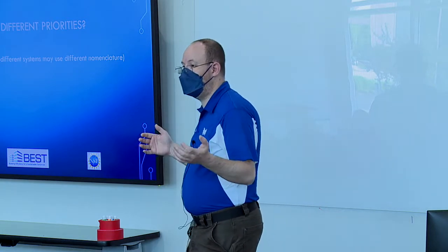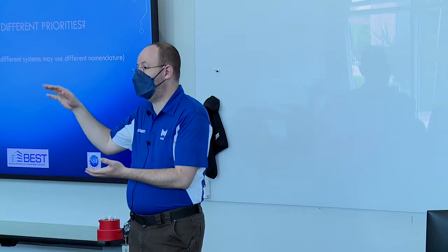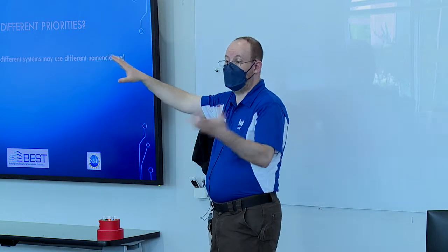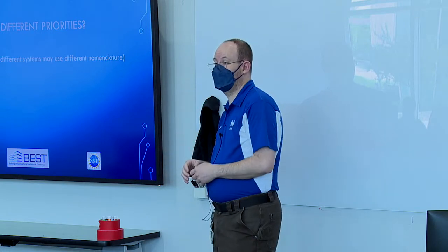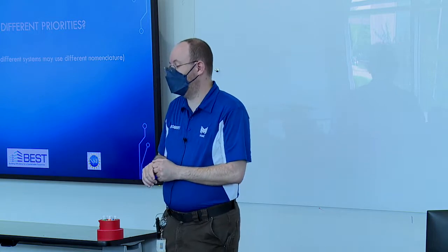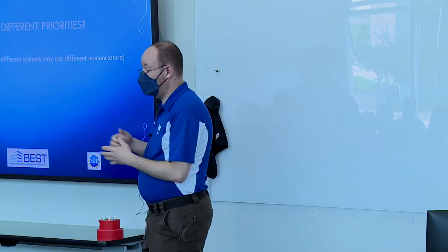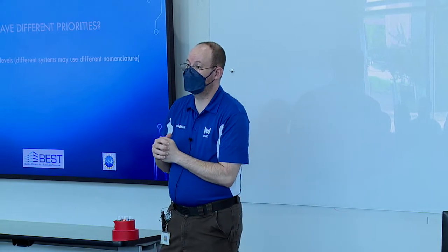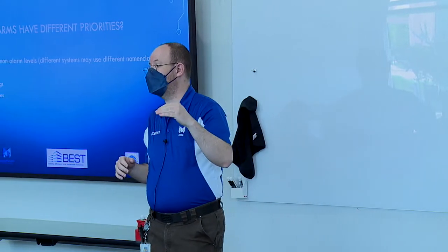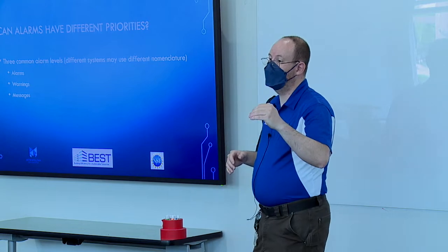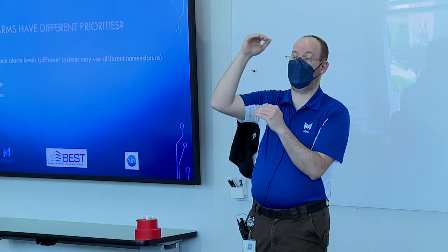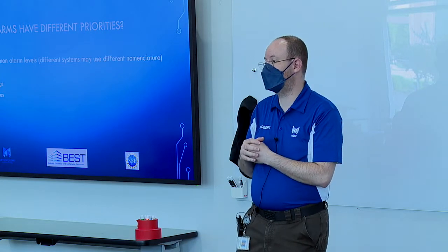Maybe we can let it float for half an hour while we deal with something that did fail. And we can come back to it and reevaluate, and get the result of another alarm. Yep. And oftentimes, warnings will escalate into alarms. So maybe it's 76 degrees in here now, that's a warning. If it crosses that 80-degree border, maybe that triggers an alarm.